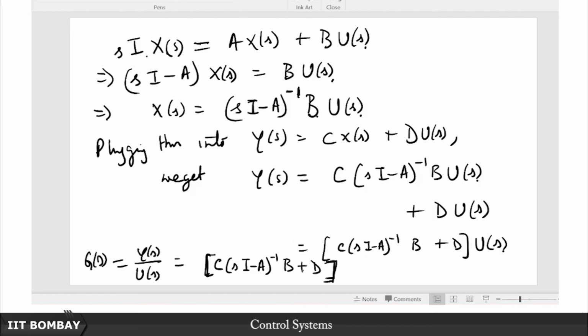So hopefully with that we have now seen how to go back and forth between a transfer function and state space realization. We have also seen the phase variable method, which is an easy method to convert the ODE directly into a state space form. An nth degree differential equation is converted to n first degree differential equations, very conveniently.